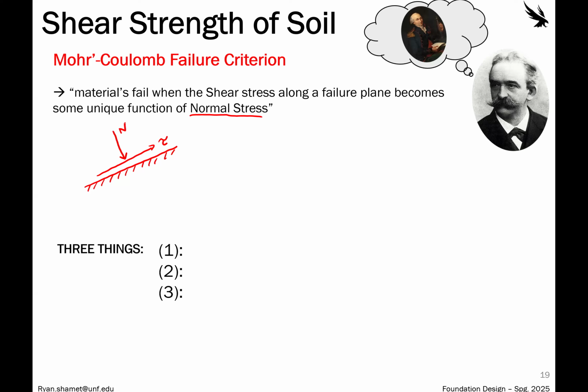This is something from physics, right, that we've talked about in Geotech 1. Think of pushing a box on carpet. The heavier that box is, the harder it is to push it on the carpet because of the increase of that friction. So we see the same thing with soil: as we increase the normal force, the friction increases and the greater the shear strength is.